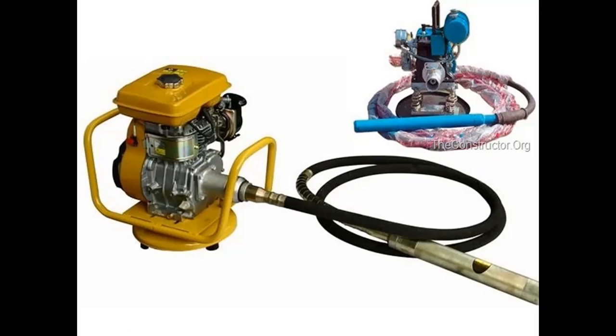so that the vibrator can help the concrete fill its voids. Between the voids, is there any air voids or water voids? While these types of vibrators are used, you can observe at construction areas that the water content present in the concrete mixture can be seen moving upwards, so that the base can be filled with aggregates and cement particles, and their voids can be filled.